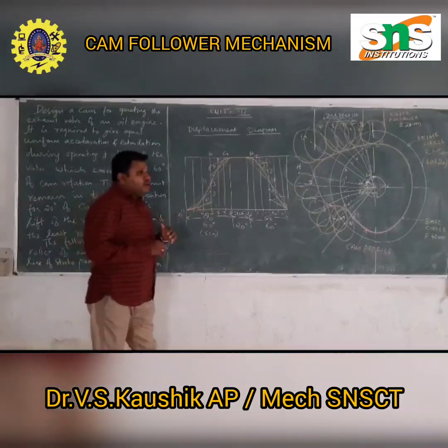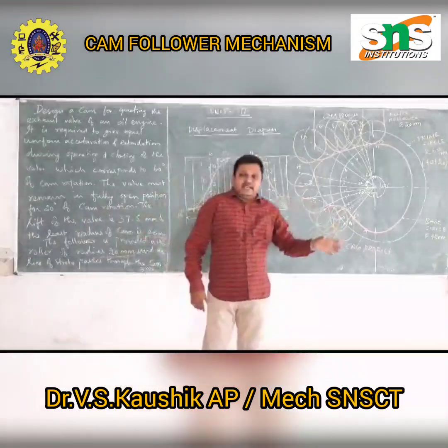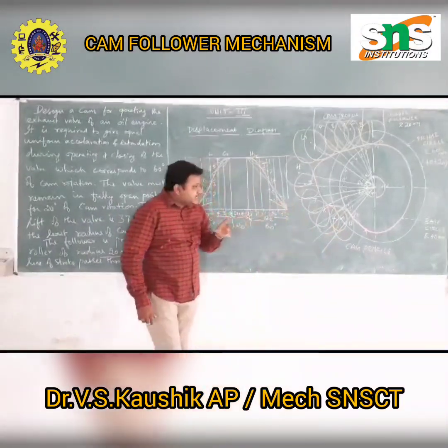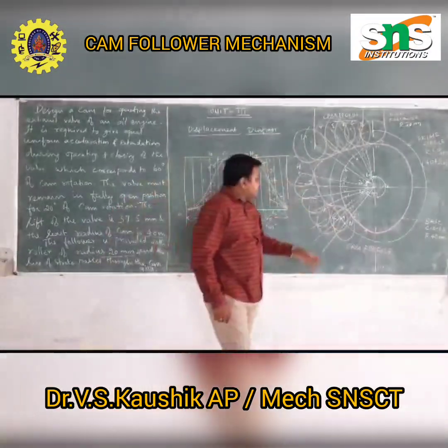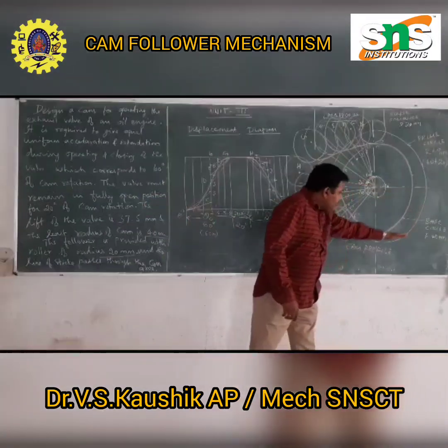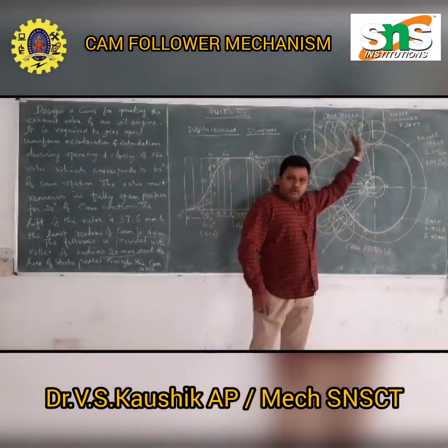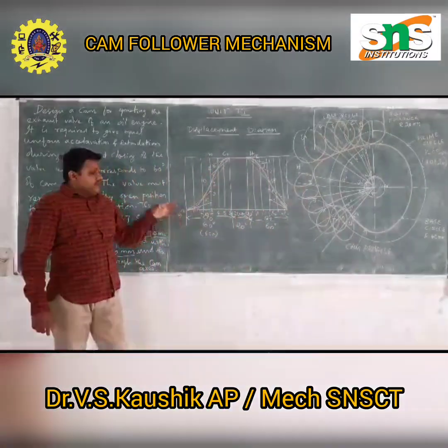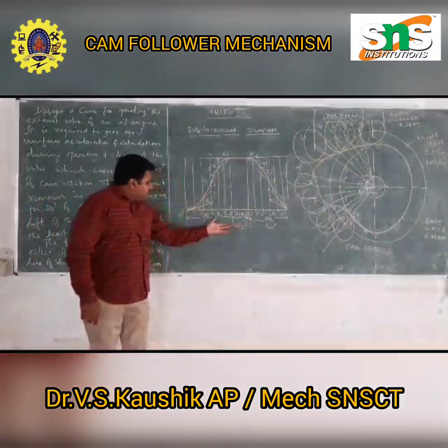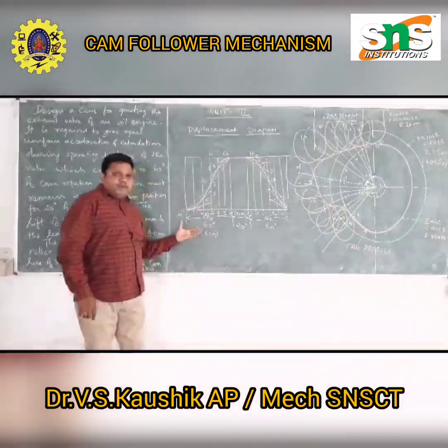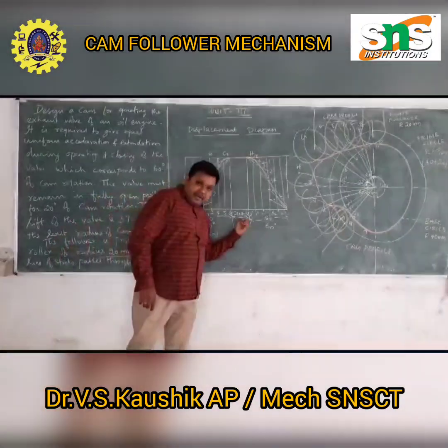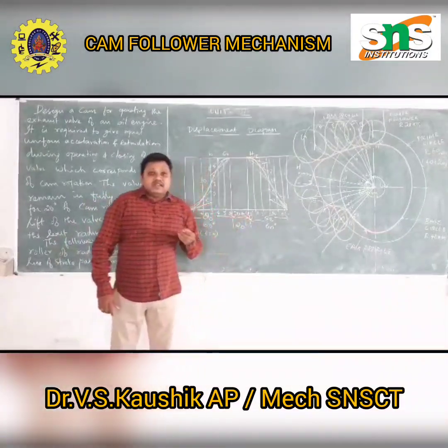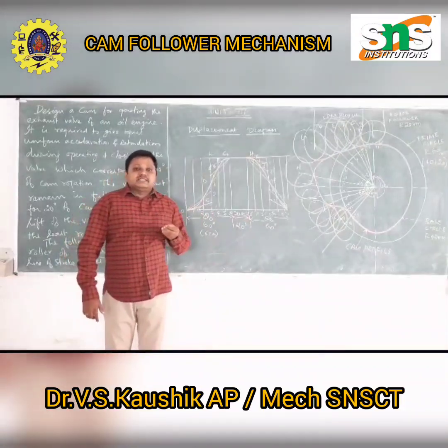Normally the cam will rotate 360 degrees. The cam rotates through the complete circle. See, this is how the cam profile rotates, and that is what is said. First 60 degrees it opens and then it remains in dwell. Dwell means the motion is at complete rest.